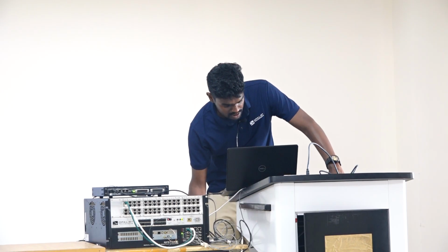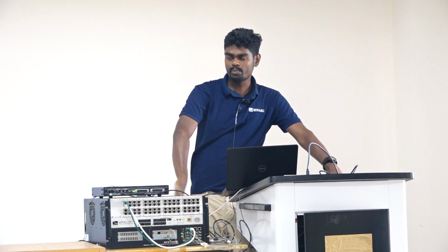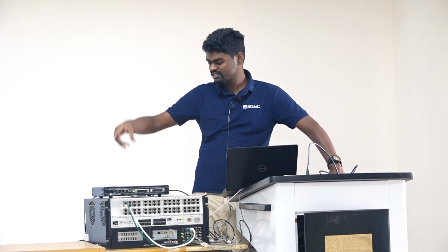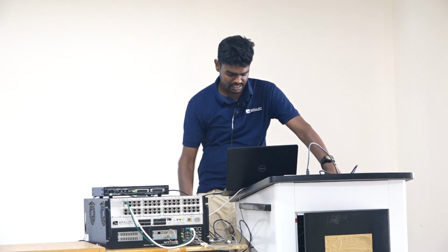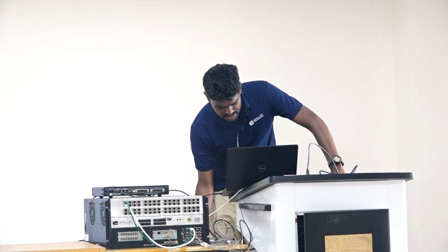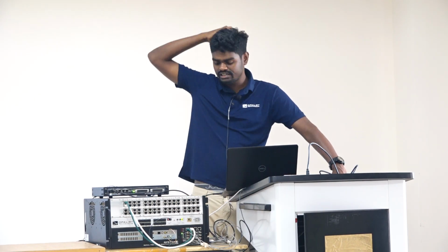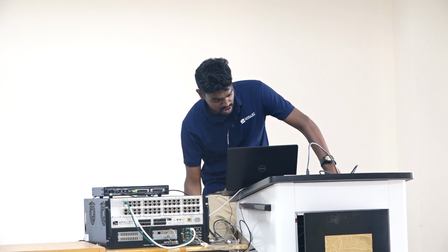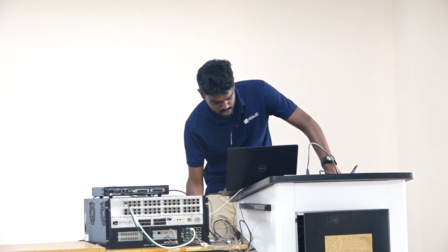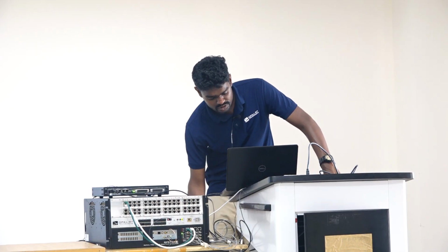So now whatever signals you get here will come from your OP5700 simulation, because from the analog out we are connecting it to analog in and we are retrieving the original signals here, and these signals will go to this controller. You can see inside this you have the control logic happening, and this controller will further give you the duty ratio or the modulation signal. That modulation signal you feed to this PWM block.